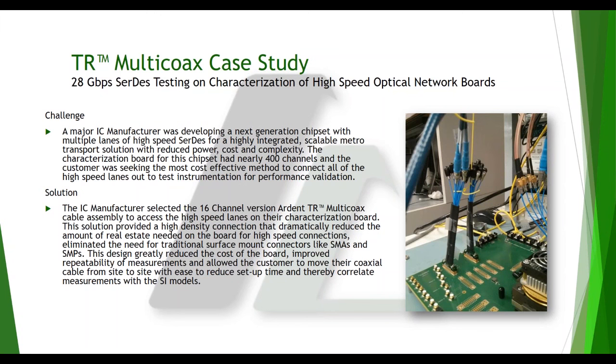So we replaced all that with just this gold footprint. And now you can see the two terminators off on the top side of the board, but they can move them around to all those footprints that are closer to the device. It makes measuring the performance of those SerDes channels a lot easier. And take it one step further, you could have used the quick latch and stepped around it instead of using the screws. Although the screws is a very quick method in itself, and we definitely give you a screwdriver to mount those on.